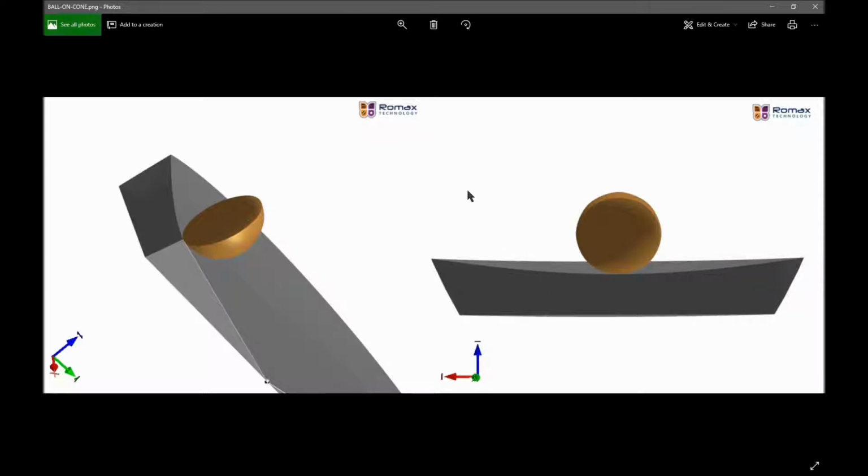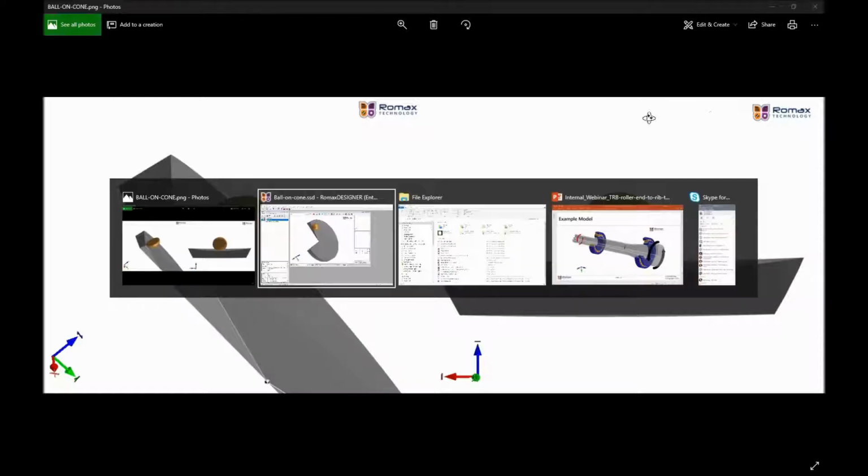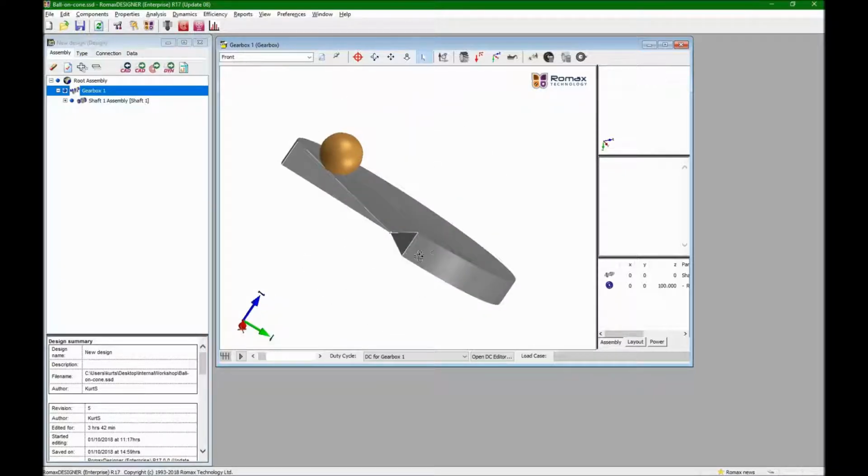As far as where the semi-major is, because this surface cups the ball, that'll be the direction of my semi-major axis of the contact ellipse. We really don't break it down to semi-major and semi-minor as far as the analysis, but it wraps the ball in this direction, so there would be my semi-major axis, because it's a ball on a flat plate, basically, in the other direction. That would be the direction of my semi-minor axis. Hope that makes sense.